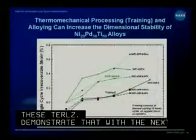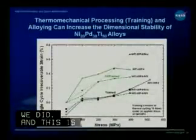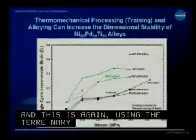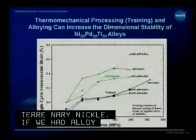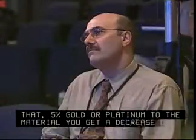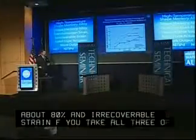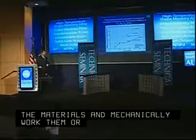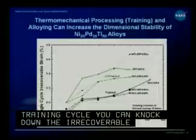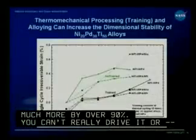And this is, again, using the ternary nickel, titanium, palladium alloy as the baseline, the 30 palladium alloy. If we add alloying additions to that, in this case we're adding 5% gold or platinum to the material, you can get a decrease of about 80% in the irrecoverable strain. Now if you take all three of those materials and mechanically work them, or run them through some kind of a training cycle, you can knock down the irrecoverable strain much more, by over 90%, though in this case we haven't optimized the situation and driven it to zero.